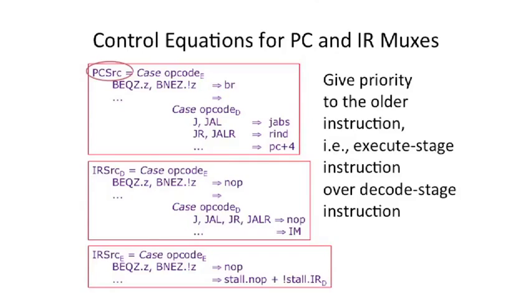We have something which is redirecting for a jump out of the decode stage. Then we have these signals coming out of the execute stage, which is strictly farther down the pipe, and this needs to take precedence over that. So if you have a branch which is directly followed by a jump, the jump is going to be sitting there trying to swing the control on the PC select mux, or the next program counter mux. You can't let that happen. You have to let the branch that's actually executing take precedence. That's really what we wanted to get across. And you'll see similarly here, the branch takes precedence over the jump and link for the other control signals.